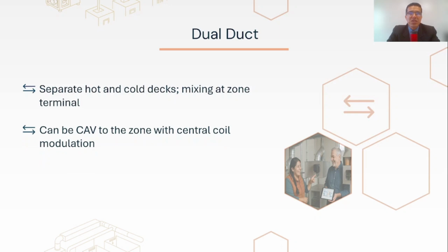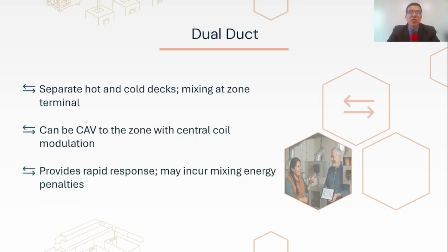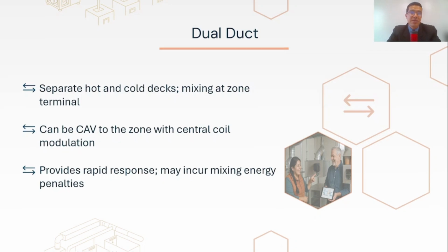Some implementations deliver constant volume to zones while modulating central coil flows to control deck temperatures. The approach can offer responsive control but may increase energy use due to simultaneous cooling and heating effects in mixing.